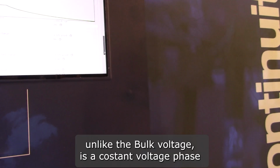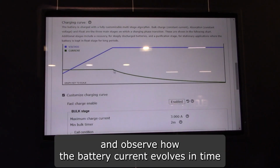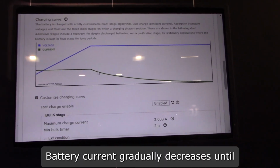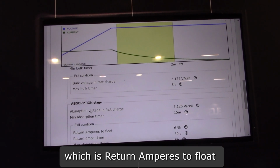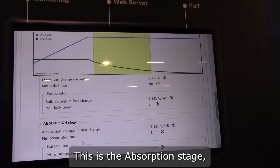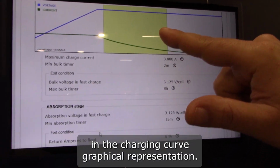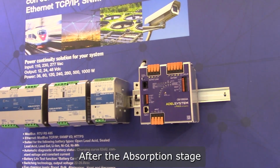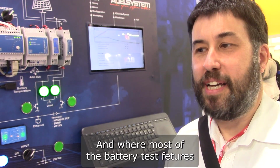The absorption stage, unlike the bulk stage, is a constant voltage stage where we keep a constant voltage at the battery and observe how the battery current evolves in time. The battery current gradually decreases until it gets below a threshold level, which is the return amperes to float. After that, the device will transition to float charge. This is the absorption stage. And we see that when we hover on a particular stage in the charging curve graphical representation, the corresponding part is highlighted. After the absorption stage, the device transitions to float stage, which is a stage where the battery can remain indefinitely and where most of the battery test